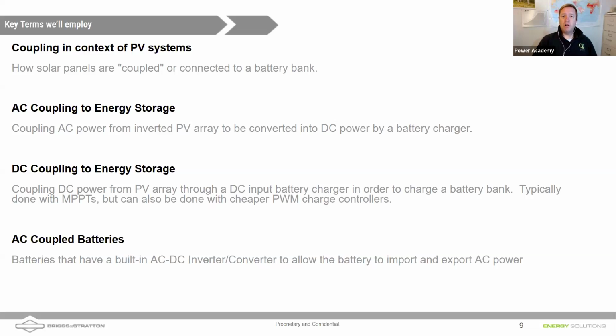Well, now that the requirement for rapid shutdown has come into play, we're already going to have module level electronics up there anyway in the form of rapid shutdown, maybe even optimization with Tigo, and they do offer that module level monitoring. So even though we're not using microinverters, we can still leverage a lot of the advantages while still being better by not having the AC to DC conversion losses.